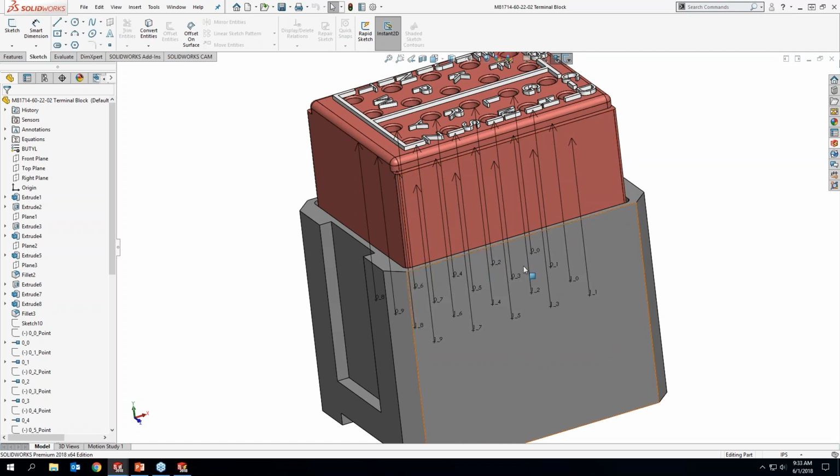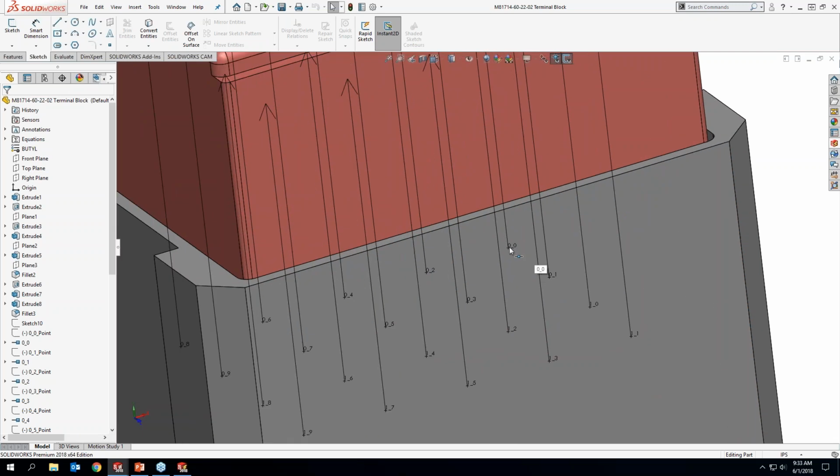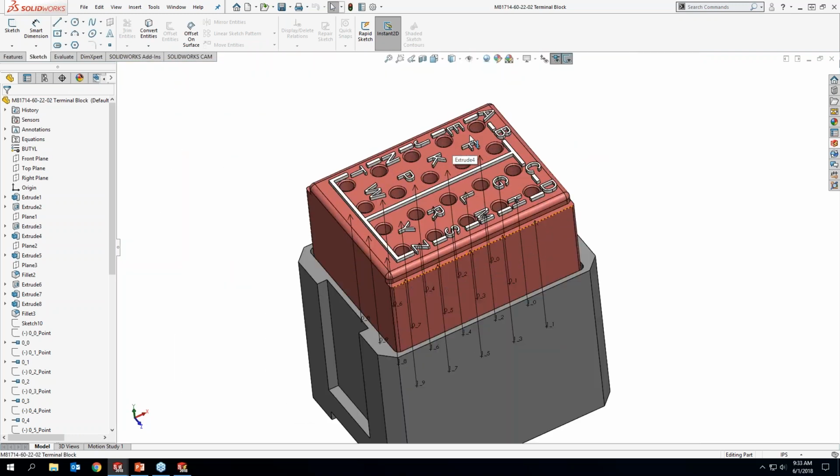These actually connect directly to my schematic. If we see here 0_0, that is actually pointing to pin 1 of my socket junction module, or in our case, pin A, socket A on this particular module. So wherever pin A is in my schematic, it's going to route directly to this particular point. Again, it's just showing that communication and collaboration between the two sides.